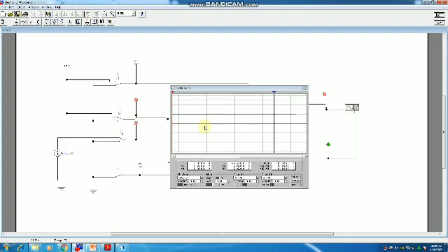The next condition is if P is 0 and C is 1. This is the reset condition. The Q remains high irrespective of the value of T. The toggle input has an influence only on Q bar. The output Q bar follows the same condition as T.